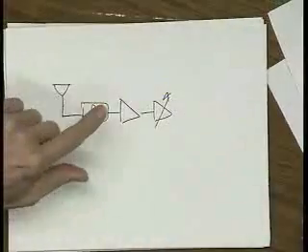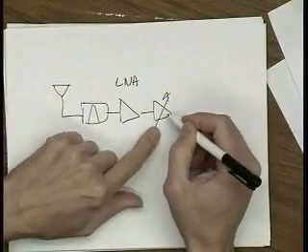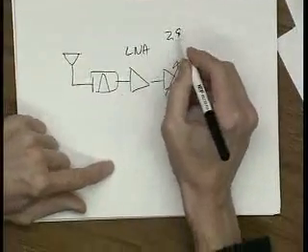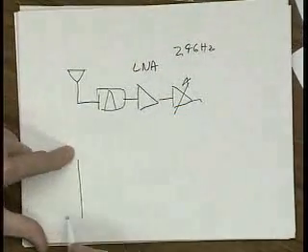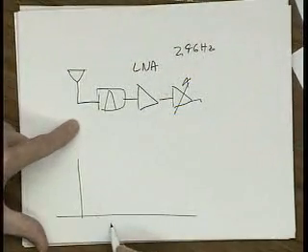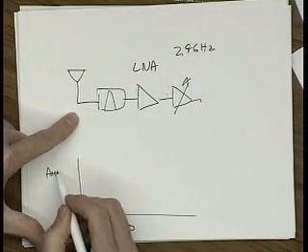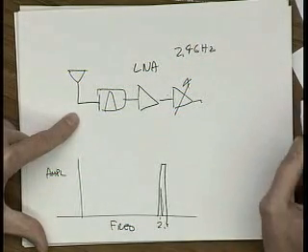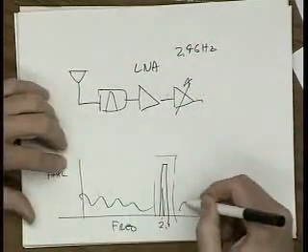So we have filtering, low noise amplifier, LNA we typically call it, then variable gain. Now this is all sitting up at 2.4 gigahertz. So all these amplifiers we have, remember what this looks like now. This is frequency versus amplitude of the signal, and this thing's sitting up around 2.4 gigahertz. There's a signal we're trying to amplify. So we can filter things here, get rid of all this other junk that's all over the place.